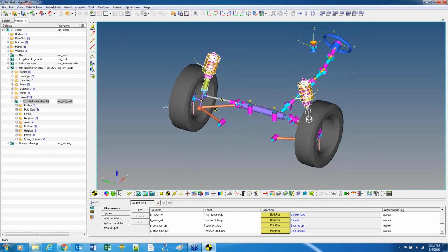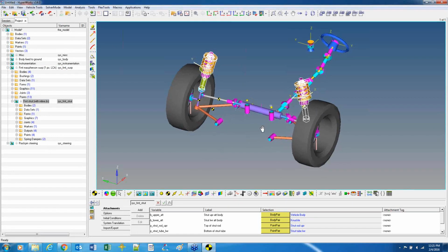At this point, I have this default McPherson strut suspension sitting there. It's automatically grounded, and I need to tell the code that I want to do something with this. Now, I mentioned earlier that for suspension modeling, quantifying how the suspension behaves as it's basically grounded is really informative about your overall design, even before you start running full vehicle events. And a very common analysis to understand that data is called kinematics and compliance, which effectively is putting in forces at the tire contact patch where it meets the ground. You could think of longitudinal, lateral, rotating, overturning. Think of the 6 different directions. So vertically, it's going to put in a displacement. In the other 5 directions, it's going to put in forces and torques, and then you can look at the results of how this exact one behaves.